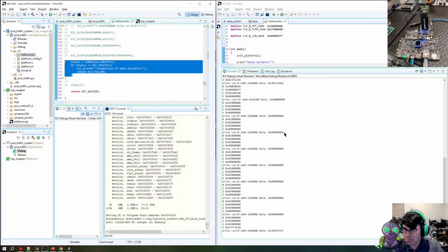So it might be advantageous to have the real-time R5 processor manage your localized hardware accelerator. I think that's a really good point. Rather than having Petalinux try to handle it with a bunch of the kernel, if it's a trusted hardware accelerator, it's a one-to-one connection, you could drop down to the R5, and the R5 could do low-level commands while Petalinux runs on the A53s.